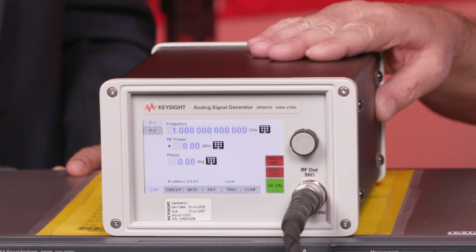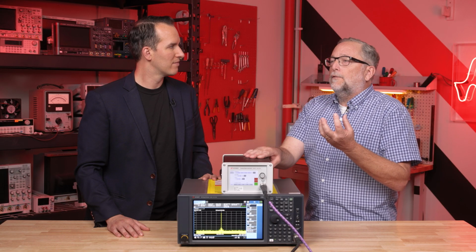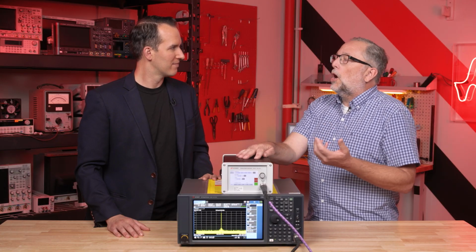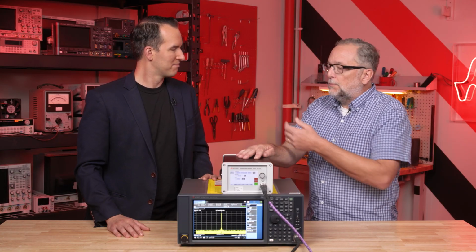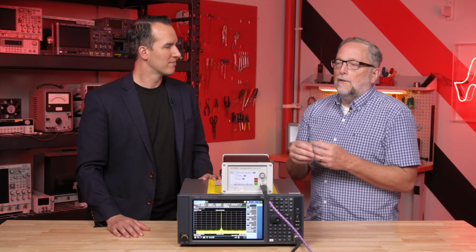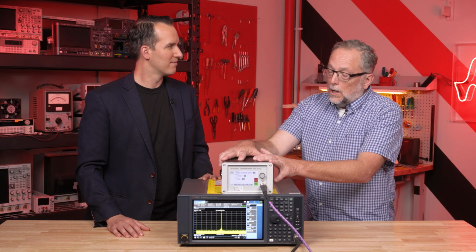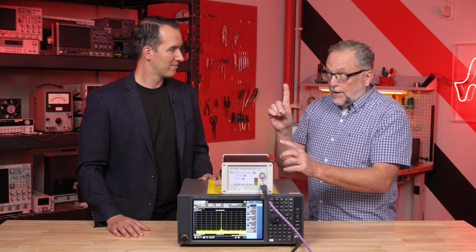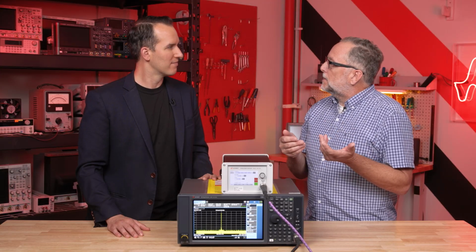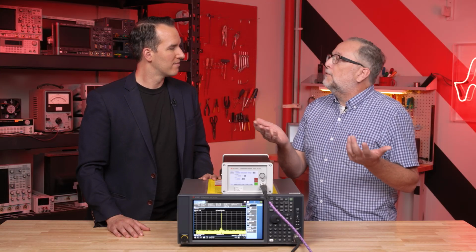That signal purity and signal quality is very important for engineers because if they're using this generator as a lower cost LO, like you mentioned before, people don't always need the full, very expensive, very heavy analog generator. If they can get a lower cost, smaller one, but still create a very pure signal, as you see there on the screen, they can use that as an LO substitute to feed their converter if they're testing a down converter, for example.